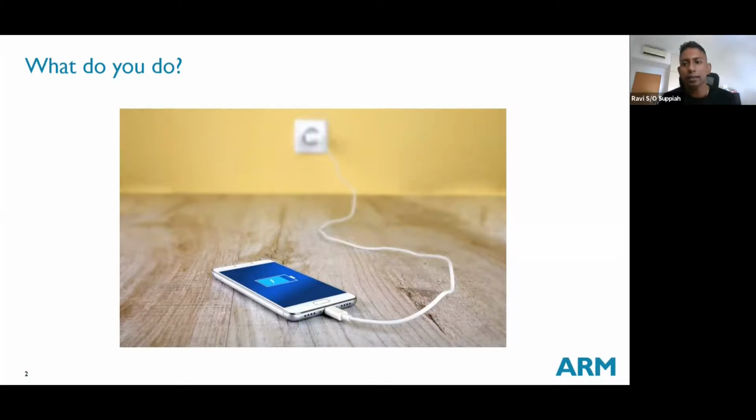Is it the initialization, something was not done, you thought it was done, maybe the multiplexing was not done correctly, the power was not set up correctly, something else that was supposed to have been configured in the setup function was not done. Okay, you thought it was there, but it was not there, all right? And because of that, it's not working. Okay, so you need to check at the software side, you need to check at the hardware side, all right?